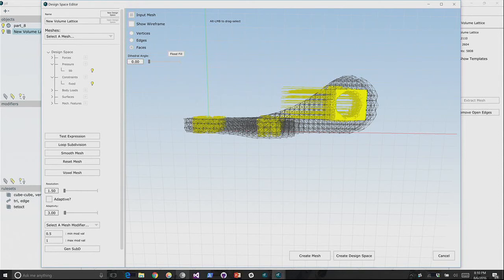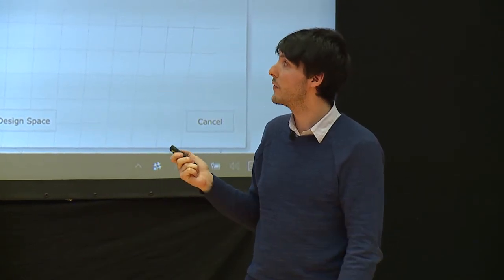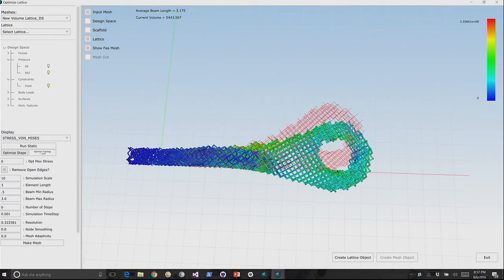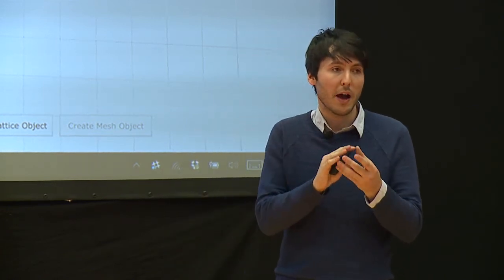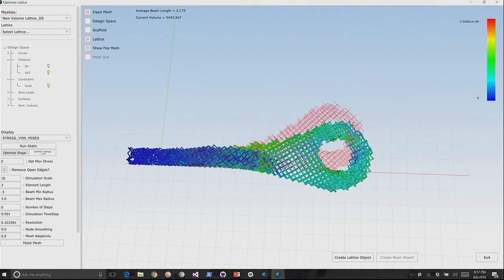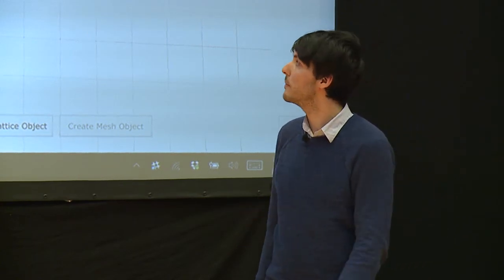We can go through and try and figure out what the best topology is throughout or what the best shape is. And so this is an example. This is in beta. It's not released yet, of a shape optimization process on a bracket where we would go through, or here we go through, and we run a simulation on just the regular thickness. And the user defines a min and max size that could be based on printing constraints or minimum size, maximum size. And then the user can input a max stress, which could be defined by the material. So like for Ti 6-4, it'd be like 860 megapascals or something.